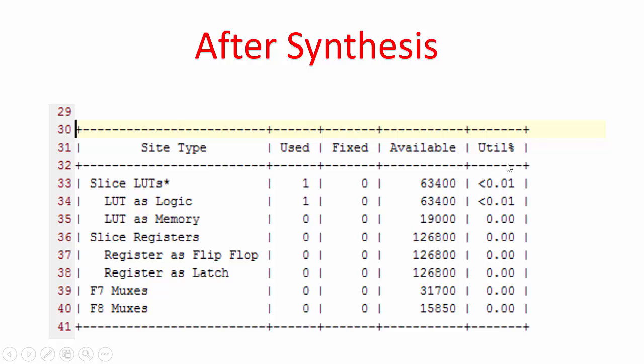In my full adder case, it is using only one lookup table, out of 63,400 available. So only 0.01% is utilized, and memories, registers, latches and muxes are not used. This is the outcome of synthesis.